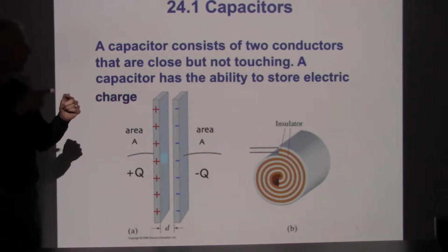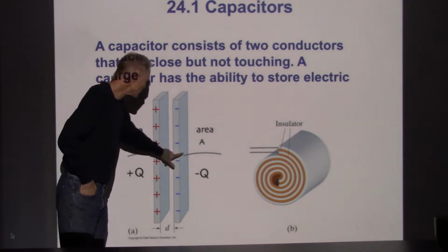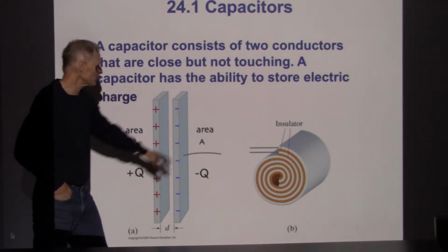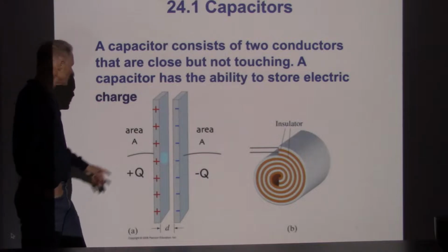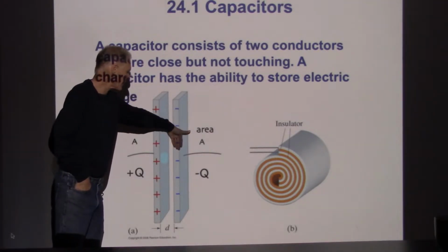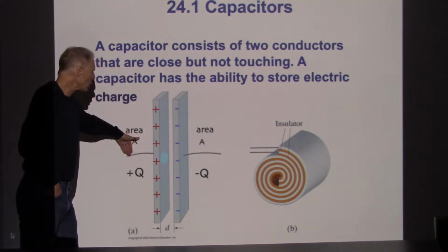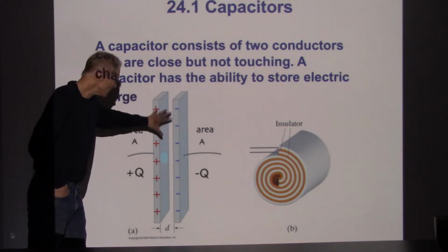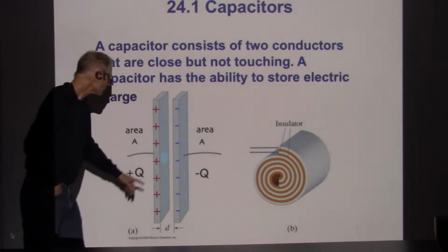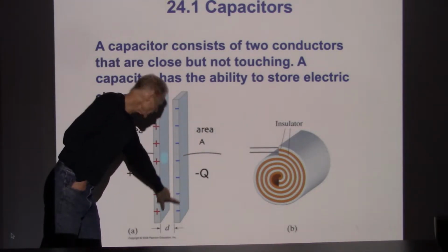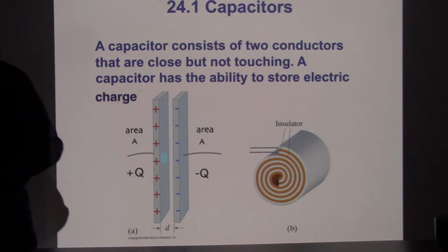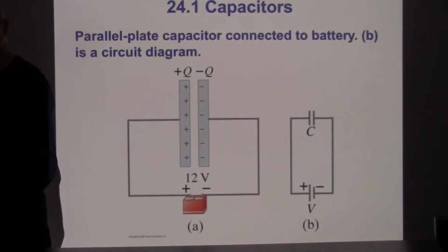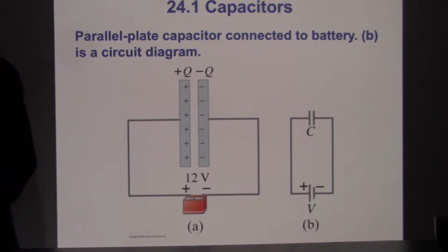Then there are wires that are attached here. Notice I have a wire attached here and a wire attached here. You can see the wires over here to the 2 layers. And that's going to allow electrons, say, coming into this side will make it negative. Electrons pulled away from that plate will leave that positive. We're interested in what are the cross-sectional areas and how much separation is there between the plates. So that's what the capacitance is going to depend on.